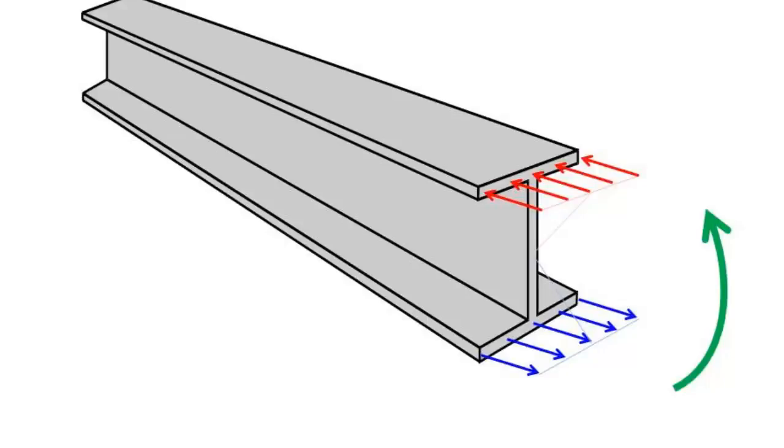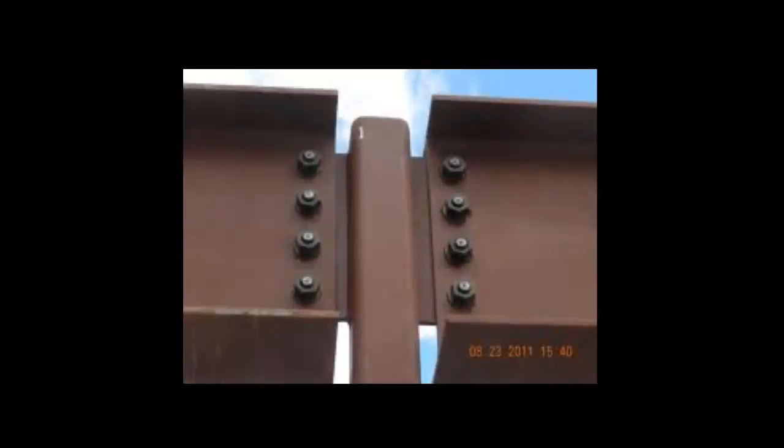Beams are often connected to columns with pin joints. In a steel I-beam, bending is resisted by stresses in the top and bottom flanges. If the beam flanges are not attached to a column, then no bending moment can be transferred. This is a pin joint. The webs are attached, restraining any relative vertical or horizontal movement, but rotation is not significantly restrained.